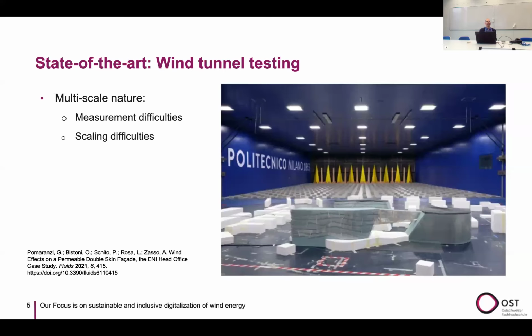This could be, and it's convenient that it's a steady state because it means the distribution is fixed. From my memory, when I was doing wind engineering for low-rise buildings, where the aerodynamics are not that important, you're right. Steady state, just a pressure load with the proper safety factors and combination factors, just gets loaded into software, and it is just a load, yes.